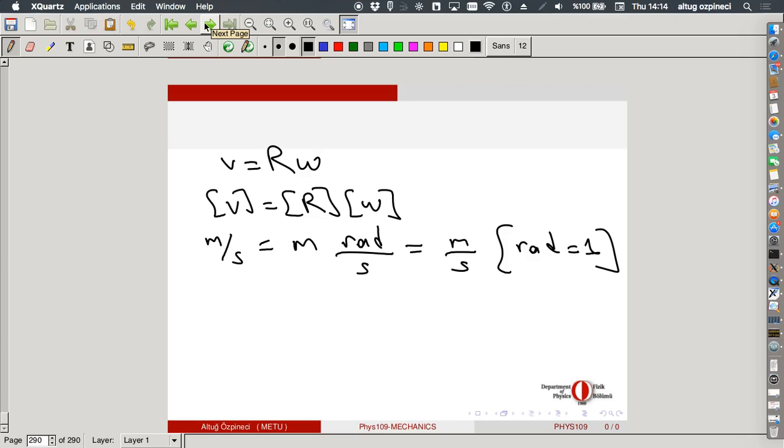What if, according to what he said, we take the limit of the radius as it goes to 0? I can take the radius to 0. This point has a radius equal to 0 and it's not moving. Now, the angular velocity is constant. For this rigid body, the angular velocity of all the points is the same. So this point again has angular velocity the same, but the linear velocity is 0, it's not moving. If I do the same thing here, it has a linear velocity.